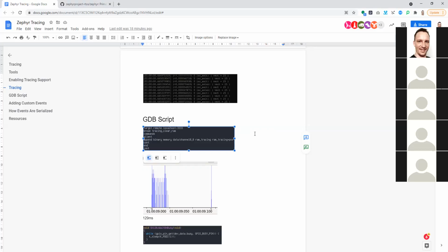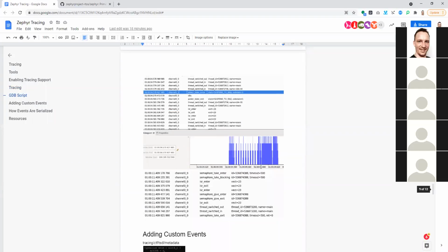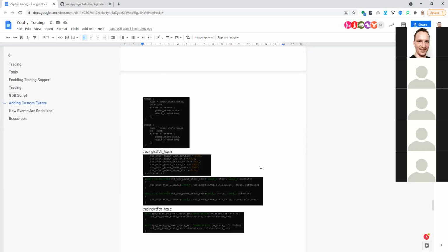So you have full control of when you're going to be pausing, and hopefully, depending on how you're using the stack, you can place the breakpoint at a suitable point where it doesn't interfere with your application. So that's one of the things that is good about using GDB directly, because you have a lot of control of when you extract the data.